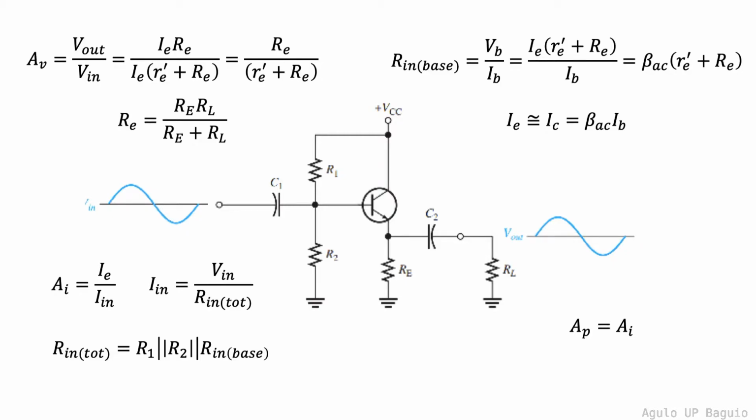Secondly, since the output is taken at the emitter terminal, there is no phase inversion. Recall that phase inversion occurs because the output at the collector terminal is taken from the difference of VCC and the output at the emitter terminal. Thus, the output simply follows the input with relatively no change in phase or amplitude, and thus the term emitter follower. If this is the case, then what is this type of circuit useful for?